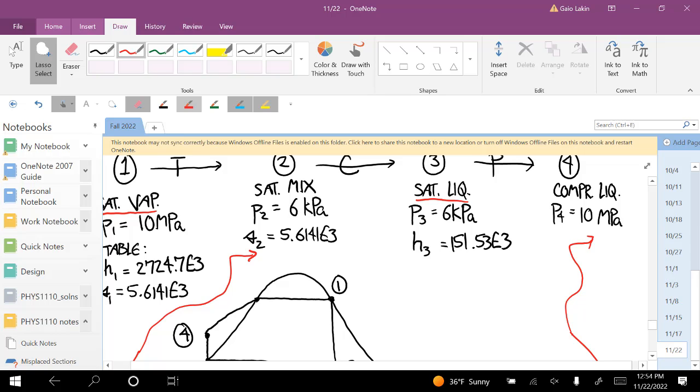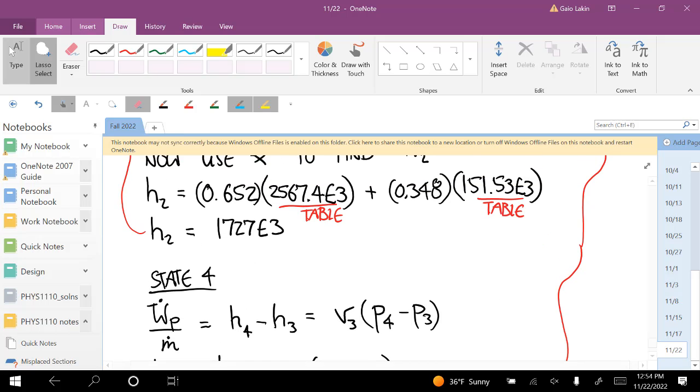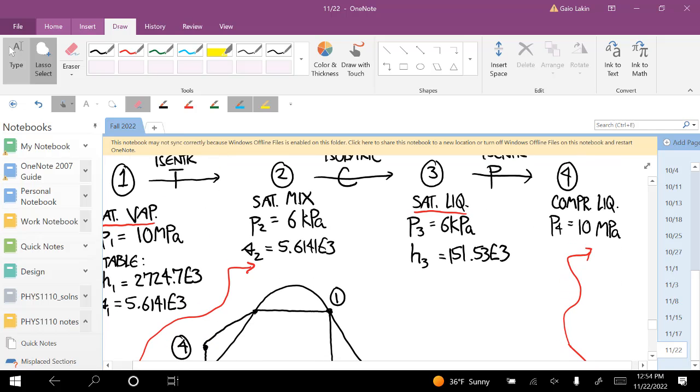I haven't even looked at what the question is asking us for yet. I just calculated the enthalpies, and then once you have those, everything's easy. And one other thing for state flows too. I know I can calculate it this way, but can we also do it the same way that we got state 2, by then just using the entropy and the pressure to...